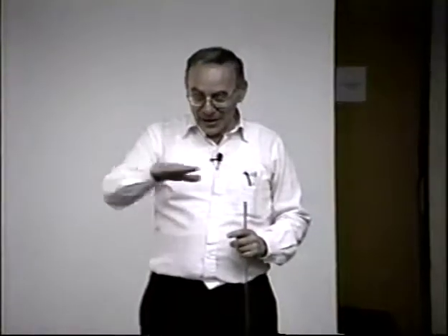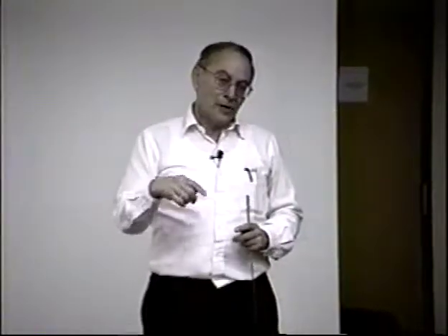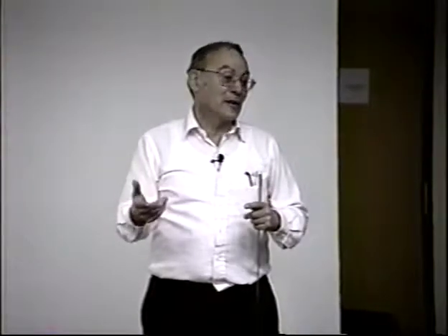And that has its own mathematical modeling of fluid mechanics and so on. But I'm just looking finally at the crystal that came out. They saw it in parallel planes, and each of them is called a wafer, and it's a circular disk of radius or diameter, say 10 centimeters, something like that. They are trying to make them bigger and put more on the chips and so on.